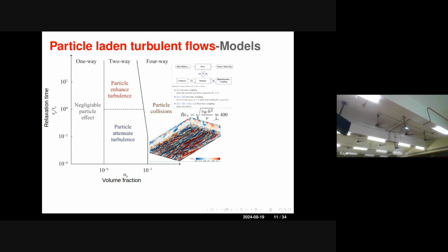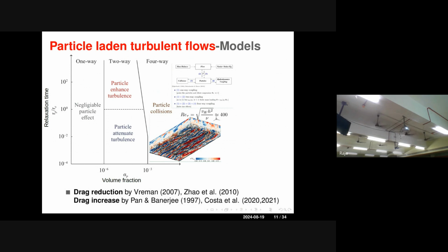For a typical industrial problem, such as a gas turbine base on which your particles are moving, or perhaps industrial reactors where particles are moving, the most preferable choice is basically going with Lagrangian entities, but writing all your forces, like inertia, buoyancy, possibly the drag and lift forces acting on it, and integrating with your fluid solver to solve it. But those studies also have their own kinds of fallacies.